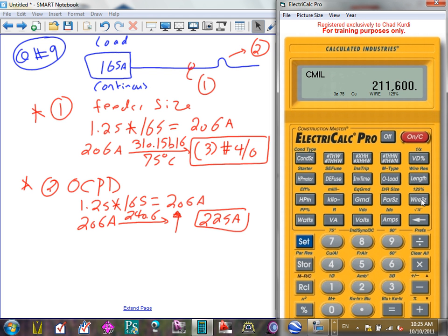See where it says it came from the table 310.15(B)(16). It's okay, 4-aught. And it will tell you, if you look, Phil, its size based on 125%. That's it. Overcurrent protection device, you can't size it from here. Unfortunately, I wish it had a button where it tells you the same thing. Should be just one button that will tell you size overcurrent protection device and give you the actual size. Doesn't have it. No, overload is different. And you're going to see that we're coming to this next week.